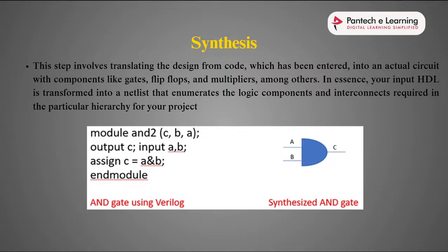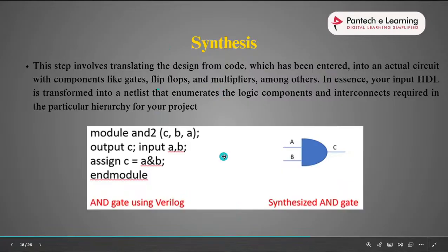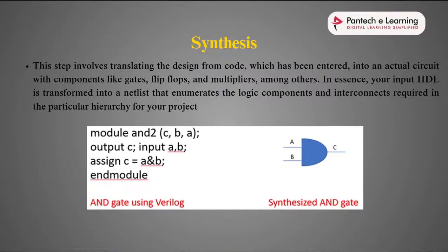Why? Because there are some constraints in Verilog. There are a lot of rules and regulations, like synthesizable commands and unsynthesizable commands, so we need to follow those. Based on that only, the tool will convert your whole code into logic gates. Those logic gates will then be assigned to the FPGA. So synthesis is on this third stage. It converts the HDL language into the synthesized AND gate. It's like converting code to gates, in simple words.